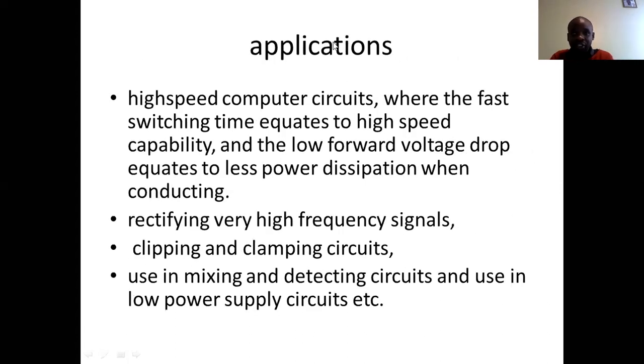These are some of its applications. They're used in high-speed computer circuits, where the fast switching time usually equates to high-speed capability. They can be used in rectification. Remember rectification, where you change AC to DC. Because of the very fast switching, they can rectify faster, especially at higher frequencies than the normal diodes. They're also used in clipping and clamping circuits, in mixing and detecting circuits, and also in low power supply circuits.